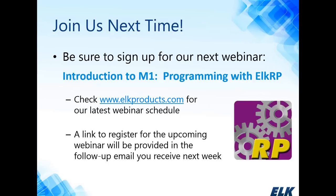If it's not broken, don't try to fix it. So that's our motto on the updates. But updating is done through the ELK-RP software. There's an update option through your send receive menu. There's an enroll update screen that populates all of the devices that are part of the system, shows you the current versions, and would allow you to update those should you need to do that.